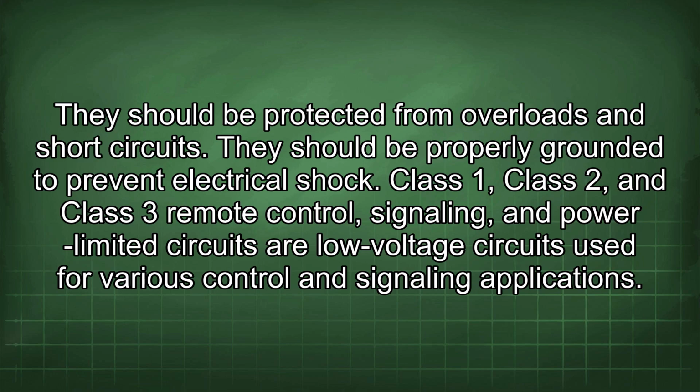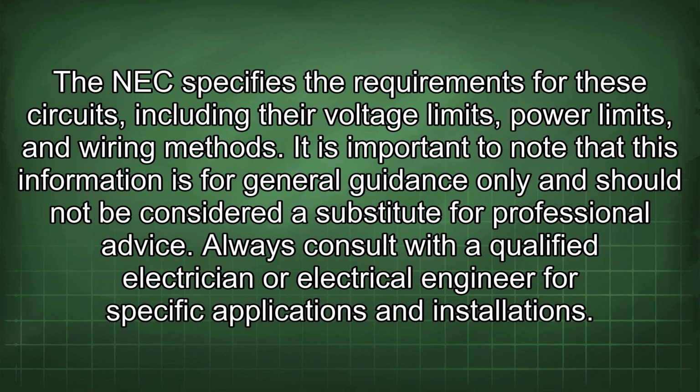Class 1, Class 2, and Class 3 remote control, signaling, and power-limited circuits are low-voltage circuits used for various control and signaling applications. The NEC specifies the requirements for these circuits, including their voltage limits, power limits, and wiring methods.